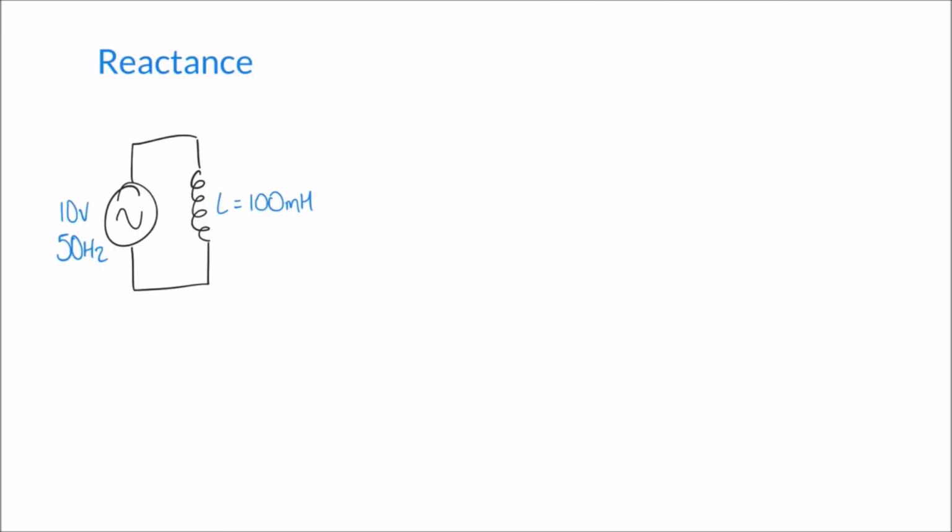Welcome to this video on reactance. Reactance is a new term that we haven't covered before, and it's given by the letter X in most formulae, and it's measured in ohms. Now, we've covered the topic of resistance, which is also measured in ohms, but reactance is not the same as resistance. We come across reactance in AC circuits.